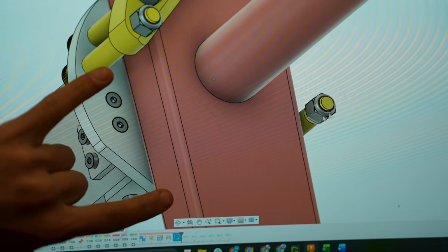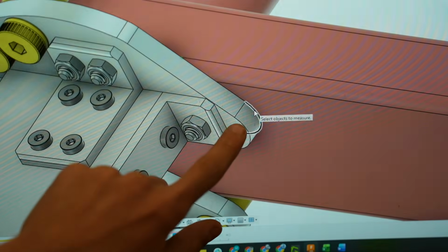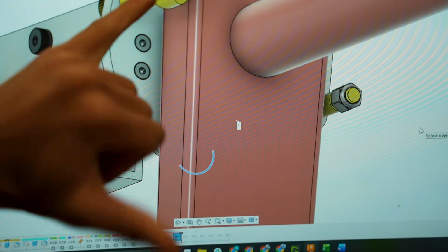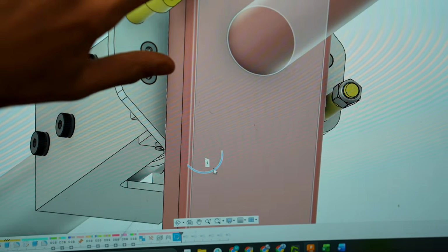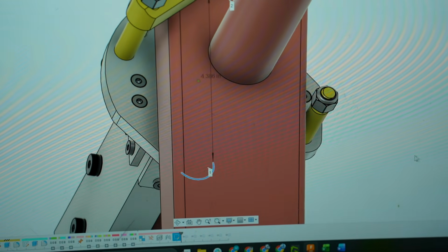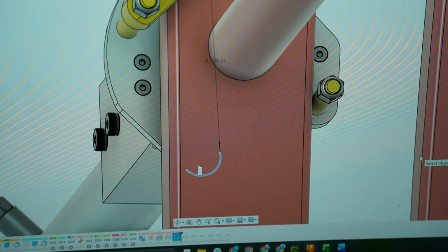Sorry, so we're actually pushing through the faceplate down here, not through our other bolt. So our reaction couple distance is going to be the bottom here to the tip of the hook there. Up to there. 4 to be conservative. So we're going to take that to be 4 inches.